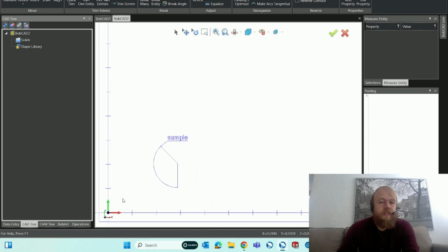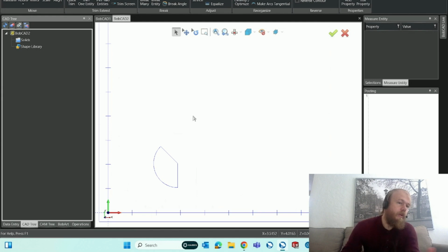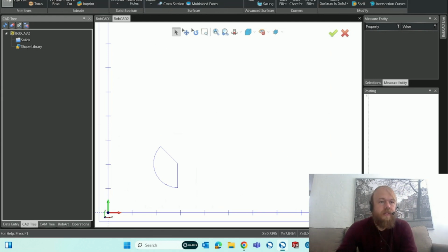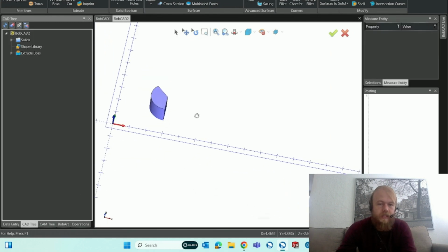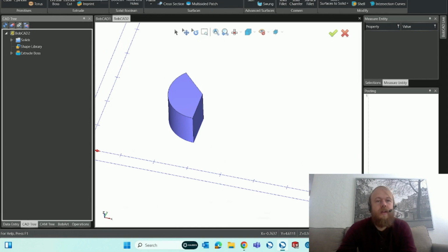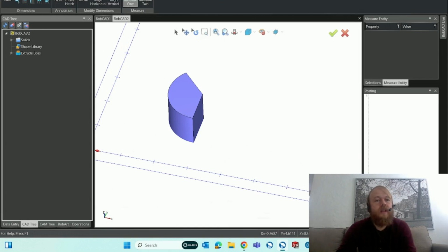The other options in here would be that I like to show over in CAD, and then we'll get into CAM, some newer features in V37, and then answer any questions that you guys may have in the comment section there. So I'm going to make this a 3D model again here. And when I have a 3D model like this, I can go to Evaluate, and we have this Measure 1 and Measure 2 entities options up at the top.